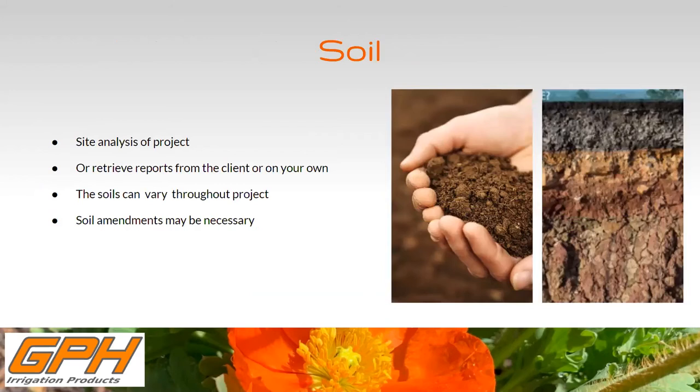I would suggest a site analysis of the project, or retrieve the reports from your client. Soil amendments might be necessary, because even on one project, you might think you have this type of soil, and on the other side of the project, it could be a completely different type of soil. So it's something to take into account.